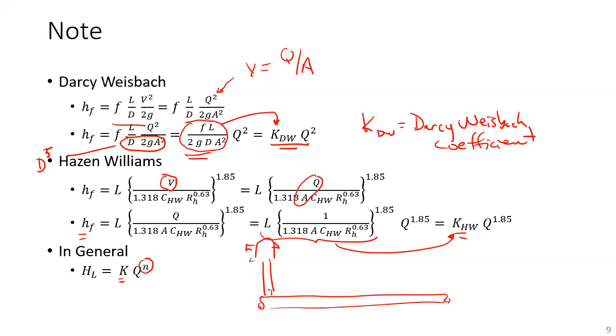So what we typically do in the field is, where you have a fire hydrant, the fire hydrant basically has a valve down on the bottom of it. And when you turn the top stem of the hydrant, when you spin that open, that opens the valve. And so what you can do is put a pressure gauge on when you open the valve and measure the pressure at one location. And then on another fire hydrant, you can measure the pressure here. And now your problem is you need to know the flow in the pipe. So what we'll typically do is open up one of these hydrants to create a really large flow.